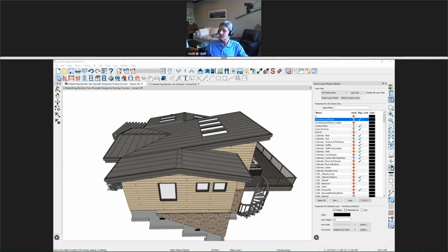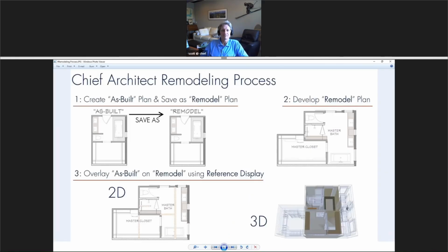So I had to pretty much start it from scratch, from manual measurements in the house to drawing it in Chief Architect. So now I'm going to finish that, set it as default, and then go back to new project, and open it as a remodeling project in order for me to add the square footage for the remodeling project phase of it.